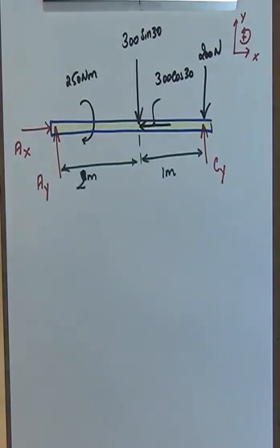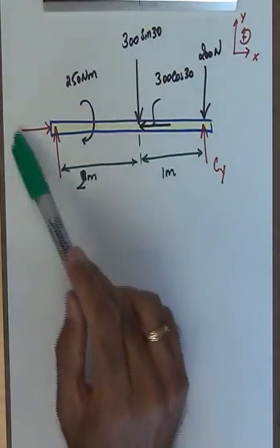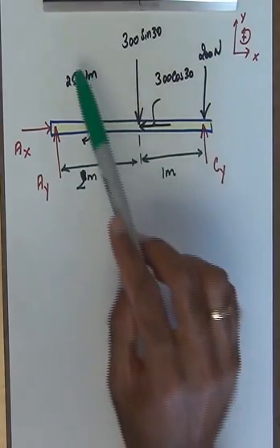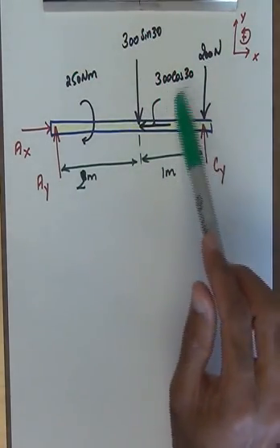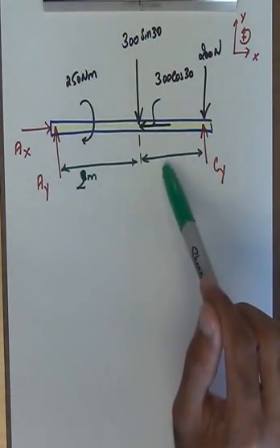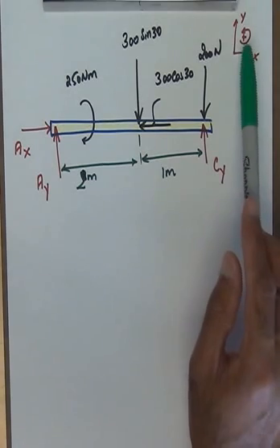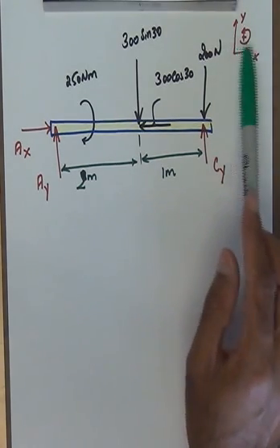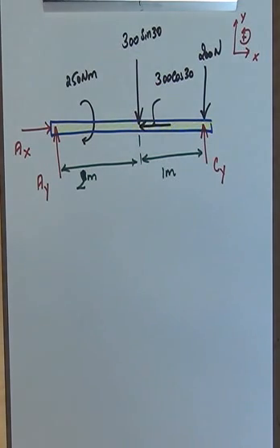What are the ingredients of the free body diagram? I have the reaction forces, all the reactions that are shown, then I have the applied loadings as you can see, and then I have the dimensions, and then I have a coordinate system where I choose things to be positive pointing to the right, things are positive pointing up, and then counterclockwise rotations are positive. And that's about it, and we start summing forces in the x, y, and we sum moments about a convenient point.